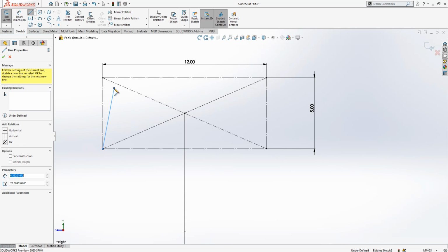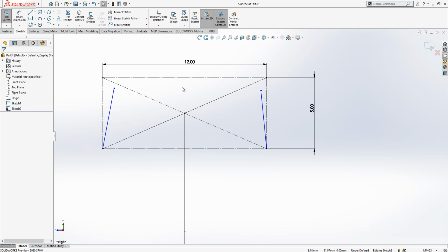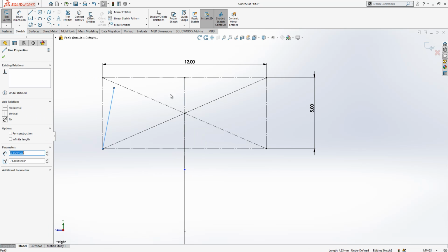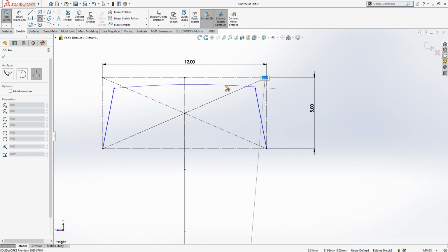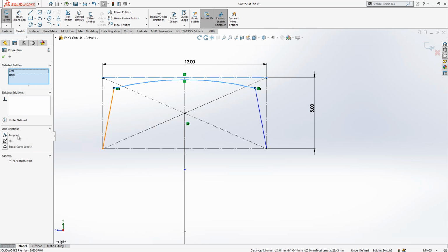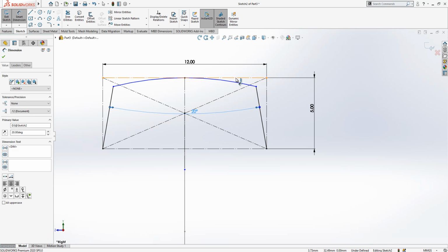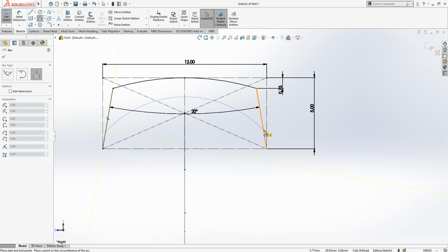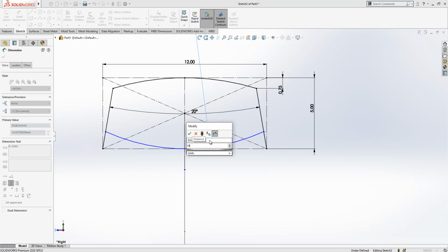And then I create here one line. And what at the other side, we could mirror it. It's easier. Create a line again. Select object, mirror. It's good. Here an arc. And we make here a tangency. So angle of this two line is 20. Height from here to here 0.75. And here to here it is just a normal arc and radius value is 16.